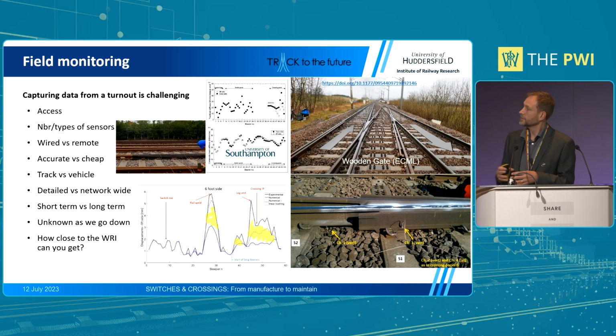And obviously, most of the crossing panel is voided. The rail weld, actually, was the major deflection at that site. So that's an area where there's localized damage, and intervention will have to be done. And the leg end area is one other area where, again, you get a lot of voiding.